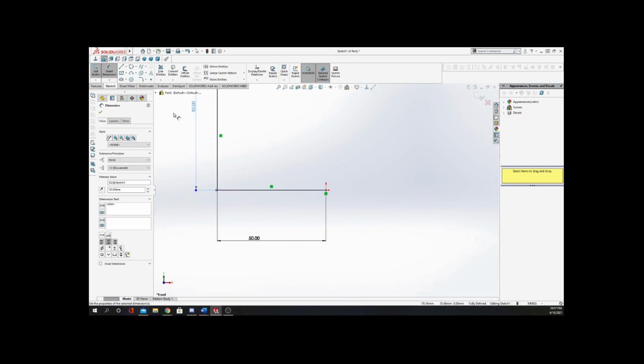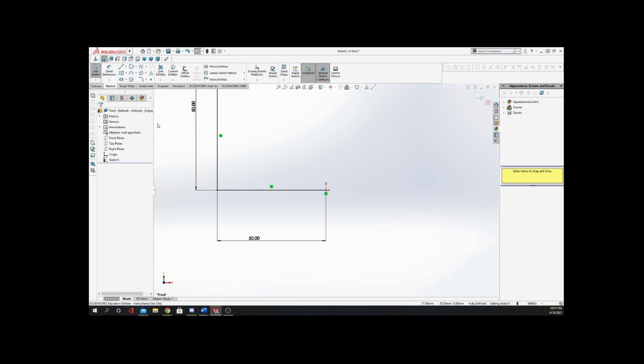All right. So check the box here, and then if you want it to do a fillet, you can click on this line, and then you click on the other line, and you can see that it gives you a rounded over corner, and in this case it has a radius of 10 millimeters. So if we say OK, you can see that that's now drawn into there. You have these other lines that are going across, but our solid line is this piece.